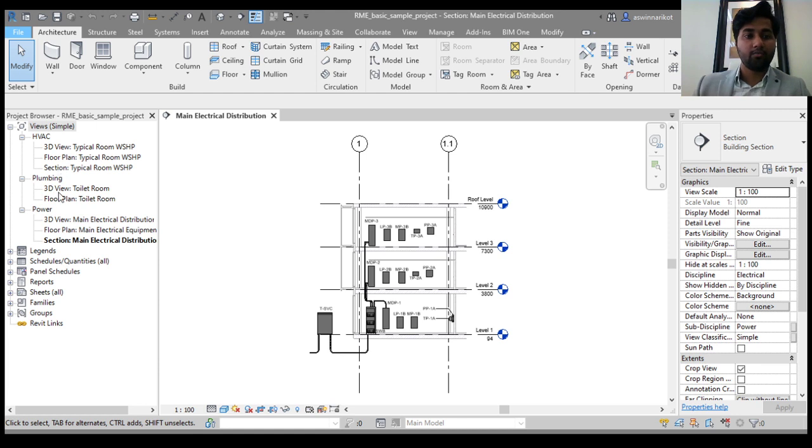Okay, we have the option to export our file into different file formats. We'll be discussing more into that in the upcoming sessions, but we do have a lot of different formats in which you can save the Revit file, other than the default Revit, which is a .rvt file. Okay, you have the option to print the page or the sheets from here, and closing the project. So you have all these options inside the file option now, instead of the application menu.